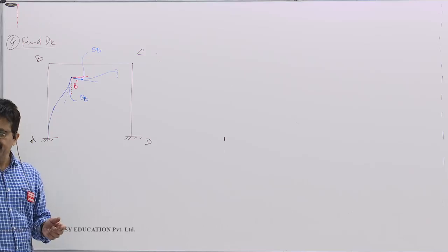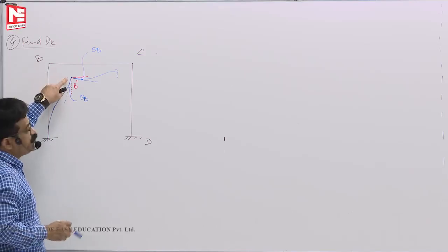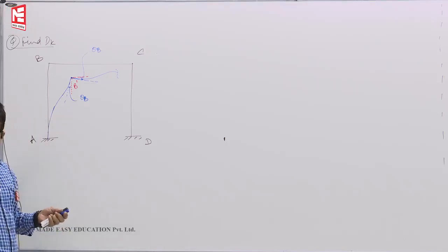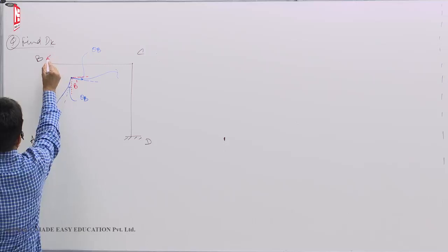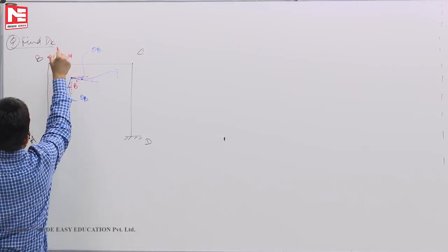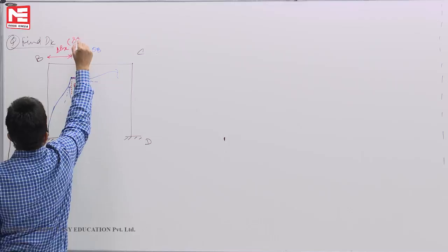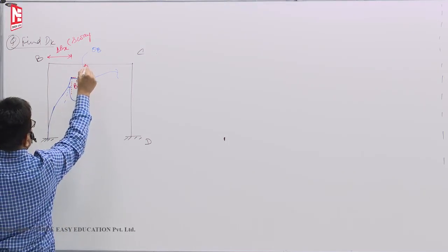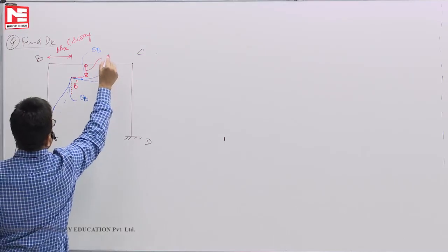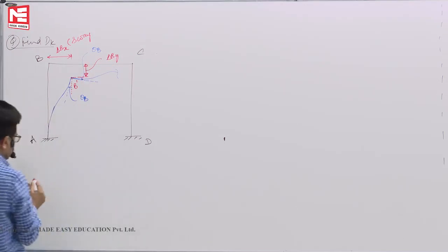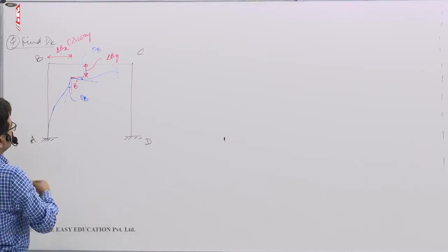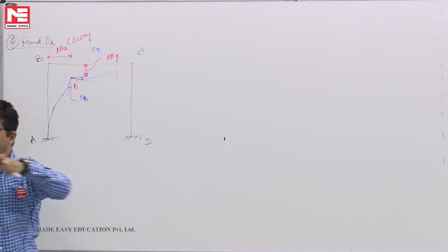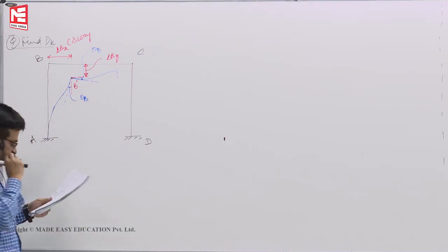Okay. So you will find that at a rigid joint in a plane frame, three displacements are possible. One is translation, from here to here, you can call it delta Bx. This way, this displacement we call it sway. From here to here, B to B dash, this is delta By, and theta B. So here 3, same here delta Cx, delta Cy, theta C.